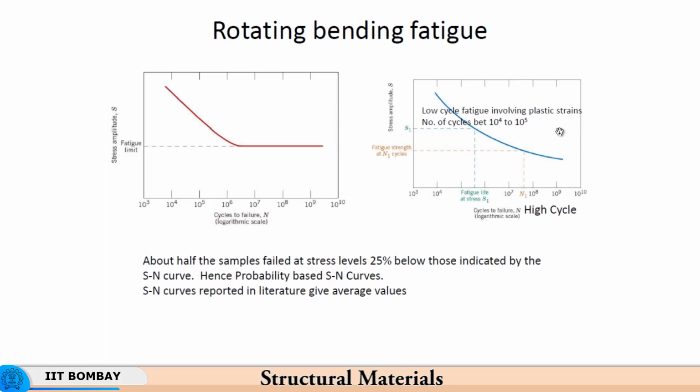So when we talk about fatigue damage, you have some immunity from fatigue damage or fatigue failure when the stress amplitude is lesser than what is given by this line. So some kind of immunity can be enjoyed by the designer from any fatigue failure.